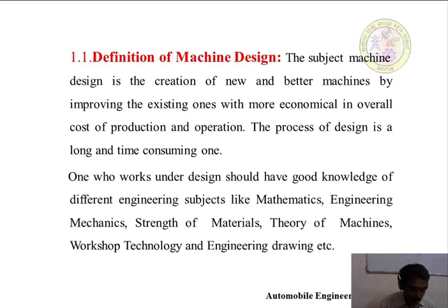While constructing joints, for example a knuckle joint, I think you might have heard of knuckle joints. Knuckle joints are used in bicycles as well as motorcycles, and sometimes also in railways. To connect two bogies, we use the knuckle joint. At that time we have to think how much load is acting upon such a joint, and on that basis only we start the construction of the knuckle joint. Such joints are used to connect the two bogies of the railway system.